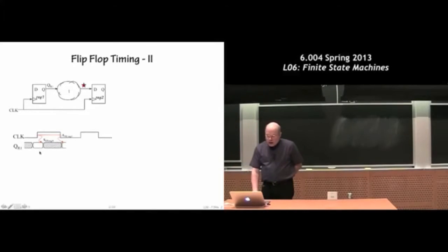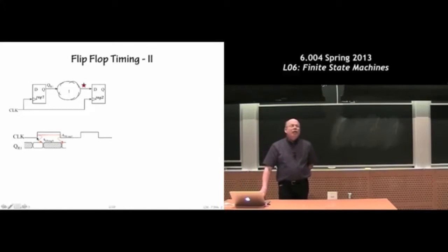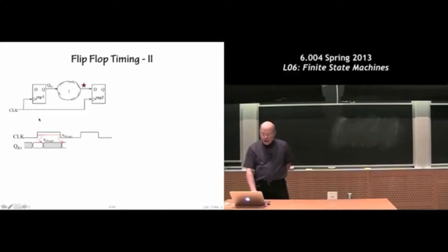And this diagram down below is a fairly careful drafting of when signals are changing and when they're the same. So the clock edge, as you can see, is in this case a square wave. It's the rising edge of the clock, which is the so-called active edge. That's the one that loads new states into the registers. After the rising edge of the clock, it takes a certain amount of time for the output of the register to get contaminated.